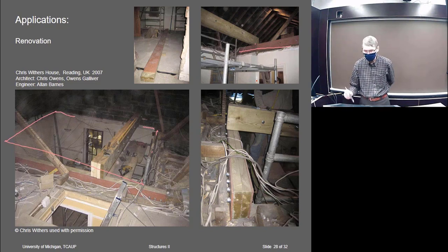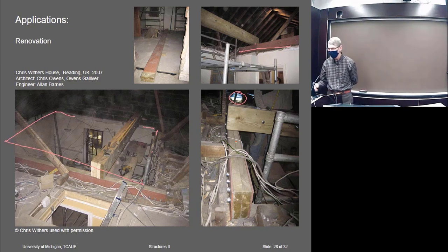So what they did is they built the flitched beam in place. They brought in the dimension lumber and the steel plates. They cut a hole in the roof and fished it through the roof, and then built this thing in place and bolted it all together and had their beam. So the moral of that is, that's one advantage of them. You can construct them in place. You can have the steel brought up separately and the wood and then bolted together, and people could do it by hand without heavy equipment.